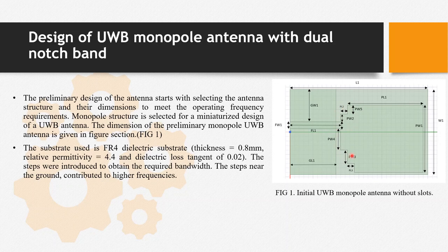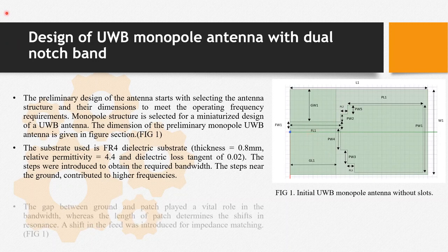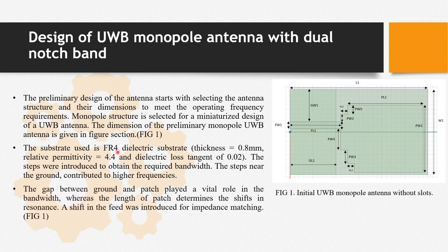The gap between the patch and the ground has played a vital role in determining the bandwidth. The nearer the steps to the ground, the more it contributes to the higher frequencies. The dimensions are also responsible for the bandwidth. The details are shown here. The asymmetricity is also introduced for impedance matching.